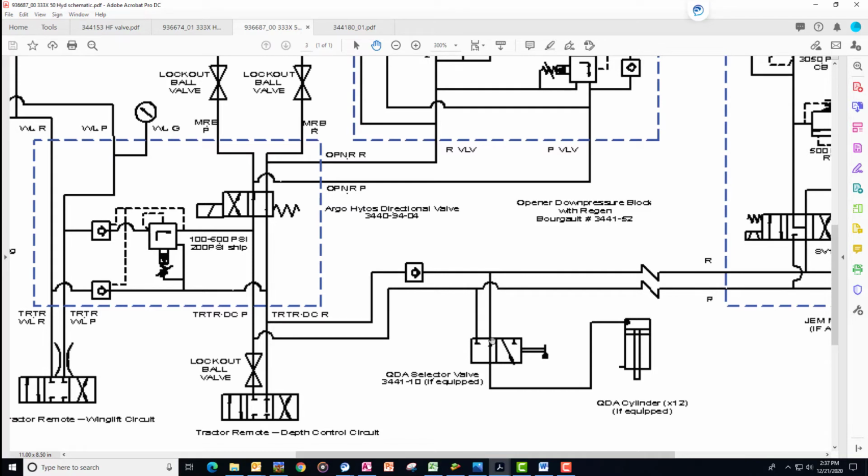You just shuttle it over. It applies pressure to the base end of the cylinders to extend the rods and raise them up. There'll be 12 cylinders per drill. And then when you want to lower them back onto the depth shims, you cycle the valve the other way, and the weight of the frame will help the cylinders down, past the one-way check, and then return to sump.